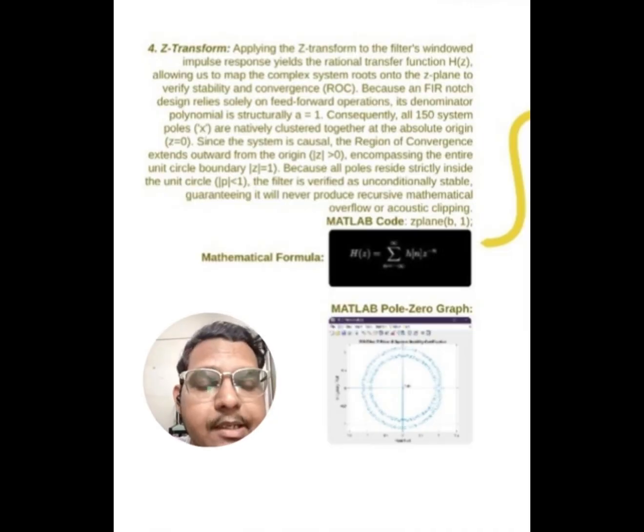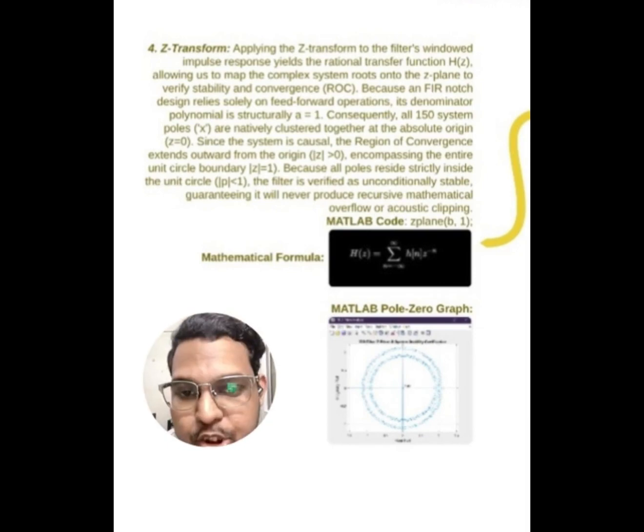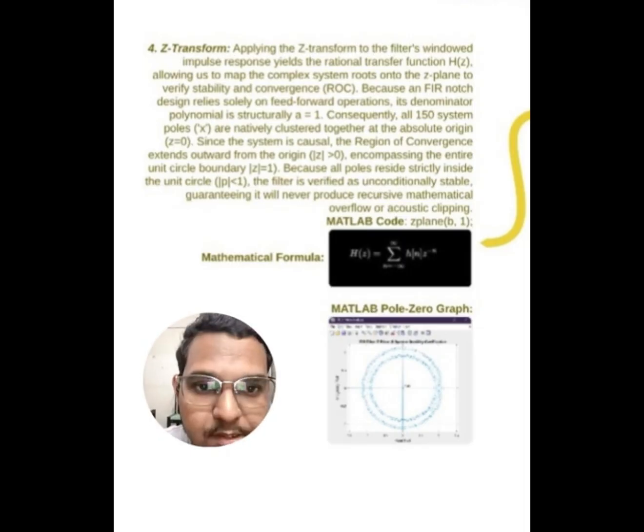All poles reside strictly inside the unit circle as well, so the filter can be verified as unconditionally stable, which means it guarantees that it will never produce recursive mathematical overflow or any acoustic clipping.